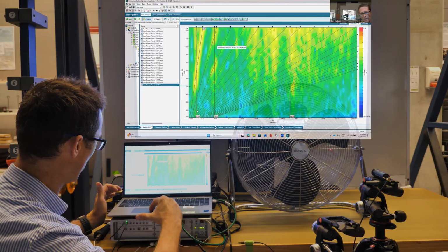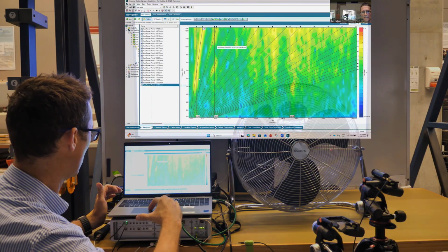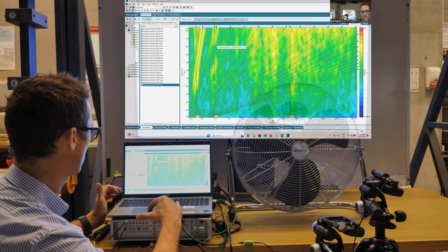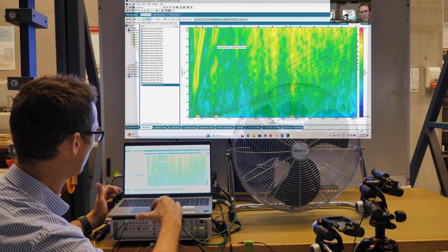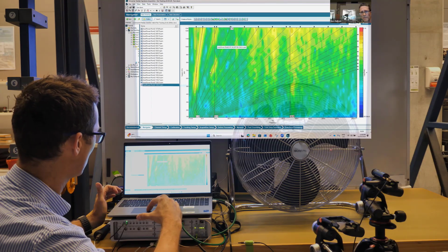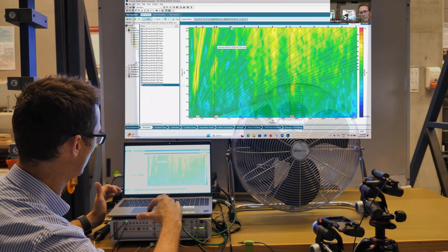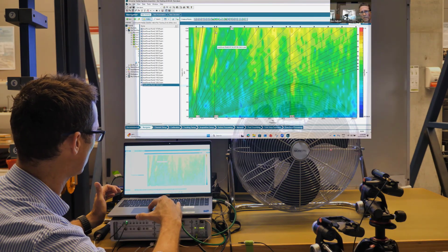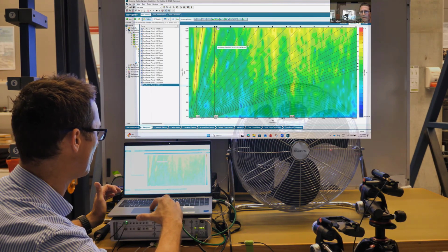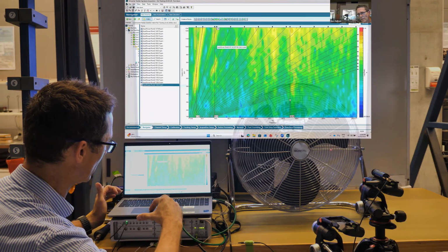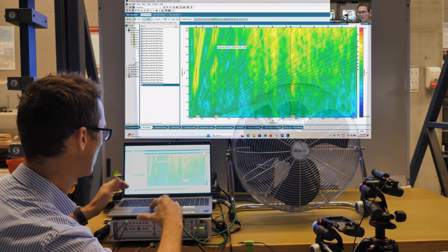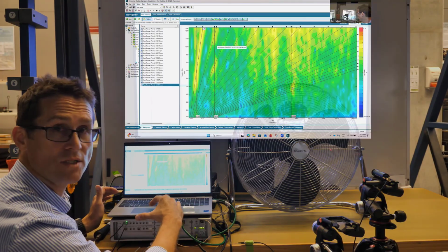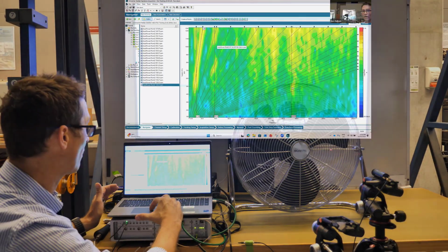But you can see quite nicely that we get higher energy levels where the first order in this case coincides with this 11 hertz frequency, and where the third order, that's the third order harmonic, coincides with this 38.3 hertz, and the second order here a little bit higher in RPM. There's a very strong order here, that 153 hertz approximately peak that we saw in the spectrum that we extracted using the modal impact hammer, the FRF.